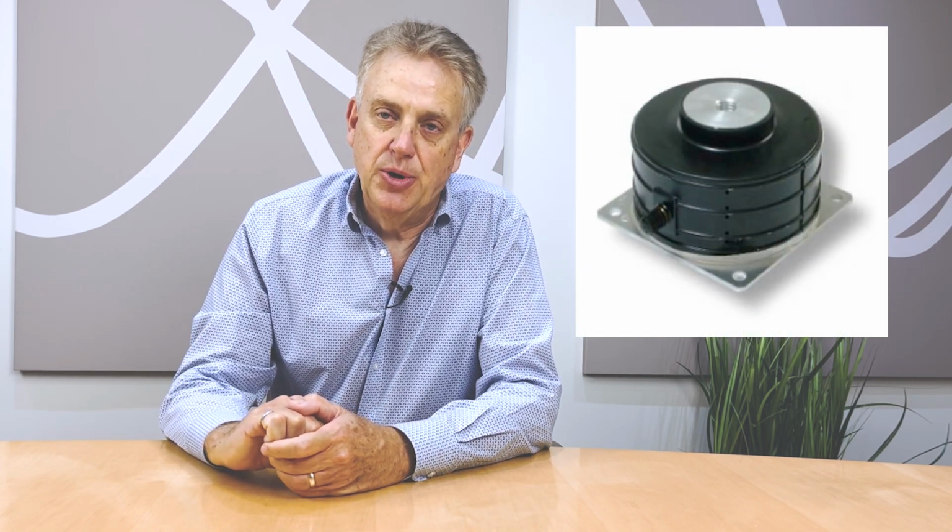There are a host of vibration isolation mounts for supporting sensitive equipment. As a rule, the performance of the mount increases as the static deflection of that mount increases. So for high frequency vibration, rubber or polyurethane pads may be sufficient, whereas in cases where high low frequency attenuation is required, we generally get into steel or air springs.